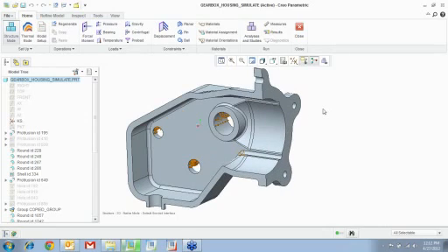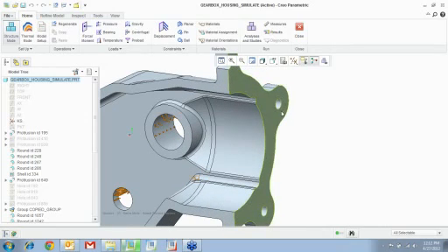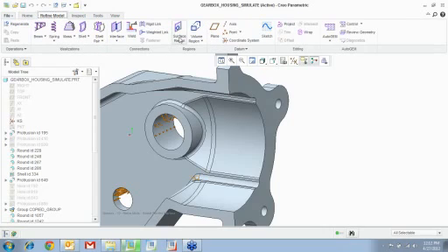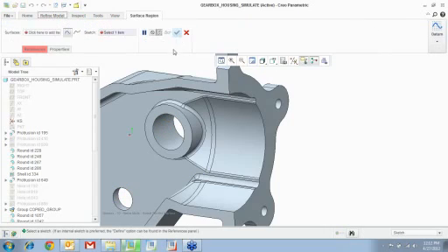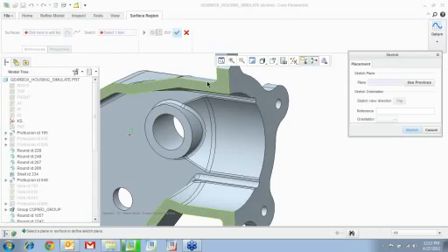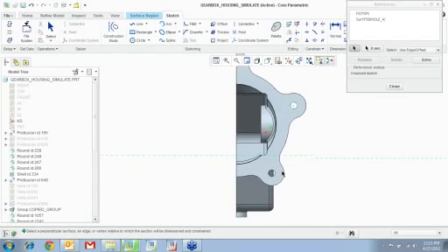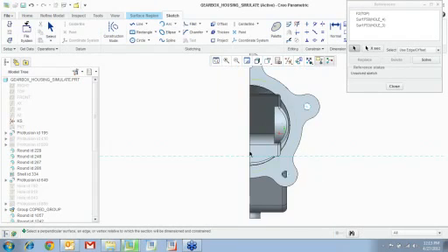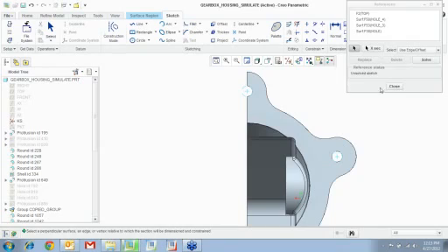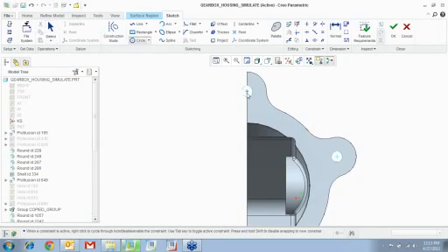Okay. Now, when you constrain the surface, let's say I'm going to put a nut, like tighten the nut, right? So one way of doing it is to constrain the whole surface. Another way to do it is to basically go ahead and create a little surface region. So I'm going to create a surface region, which is a sketch on this surface. Now I'm going to use those as references so I can create them real quick, and then stick in a circle.